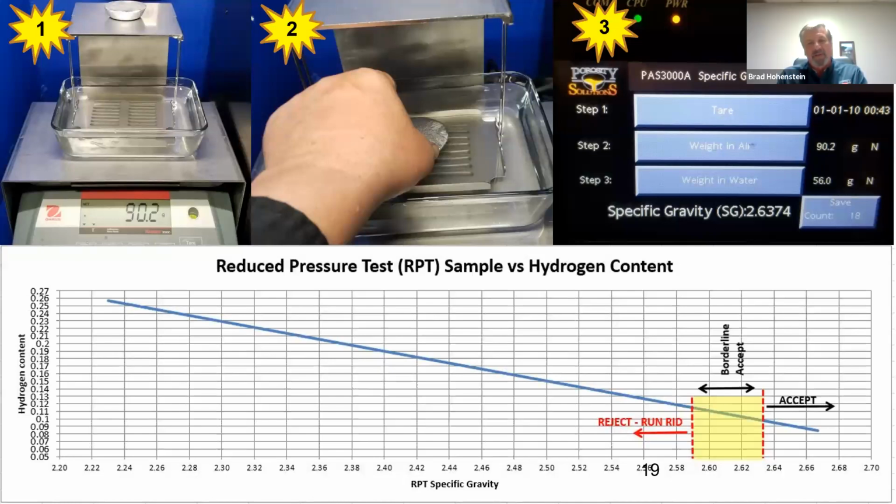Not too much. The chemistry does not affect it too much. It does some. A lot of the foundries will be running a 356 and then maybe 319, and sometimes the 356 will pick up gas a little quicker. It's basically related to the fluidity of the metal. So if you look in your book, the fluidity of the different alloys can be a little different, but it's not that much. It doesn't make a huge difference.